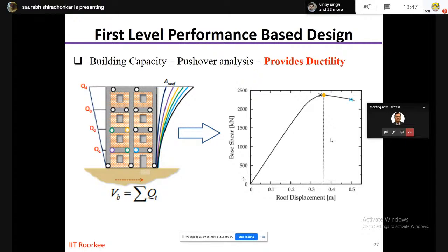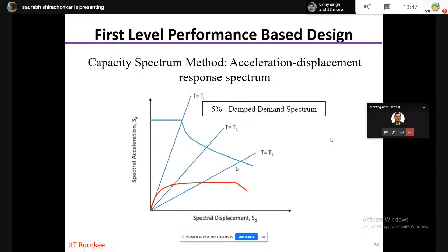And if you can recall the design response spectra, you can see that as your time period increases, your force level reduces. Now, both these things happen at the same time when an earthquake strikes: your structure is getting damaged, and because of that, your demand is reducing. But when you are analyzing the linear structure separately and the non-linear structure separately, the capacity that you got is the true capacity for the given force distribution load, but the demand that you calculated is for the linear structure.